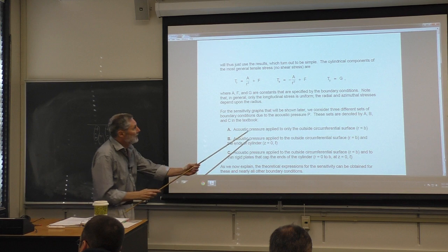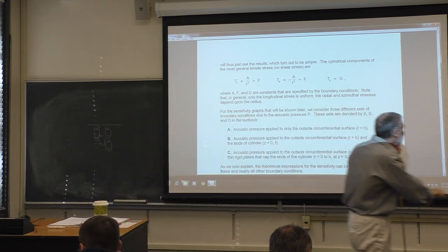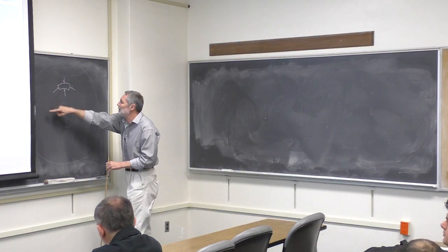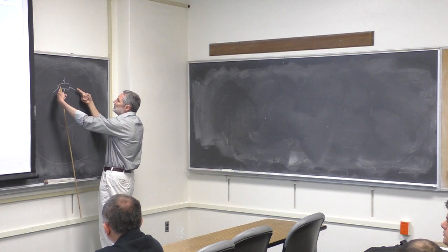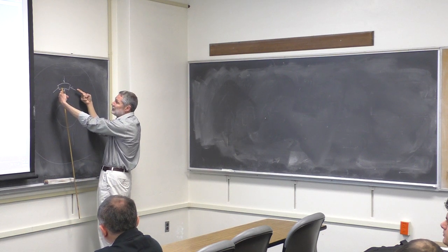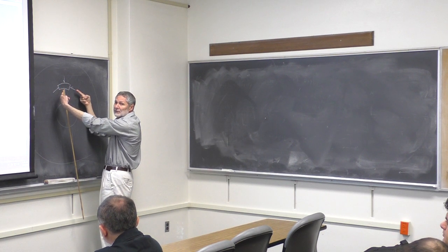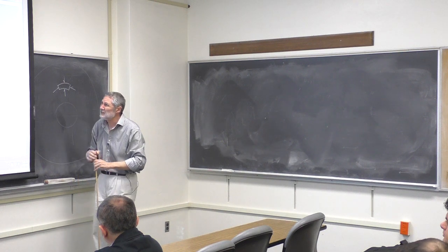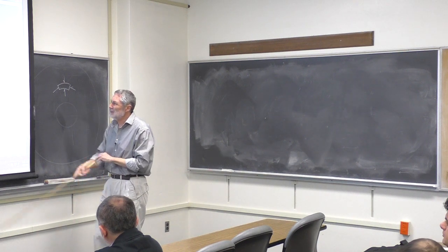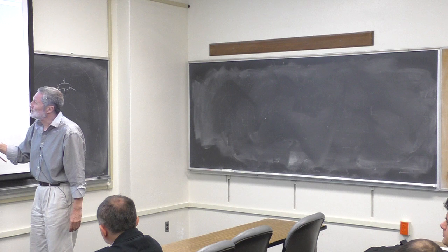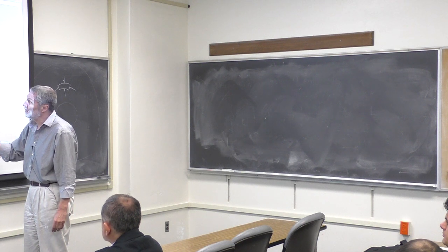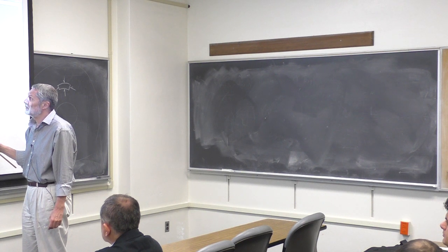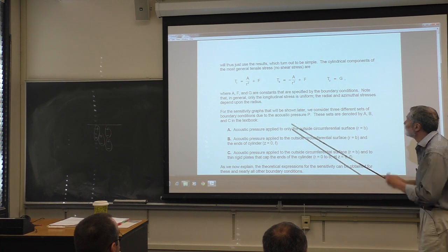The same thing happens. You can see there's a connection, what's going on radially here, what's going on here. These two stresses here don't add to 0, right? Because they're at angles here. So there's an interplay between the azimuthal and the radial. So maybe it's not surprising that it looks like this. Same A and same F, which depend upon the boundary conditions, but with a minus sign here.